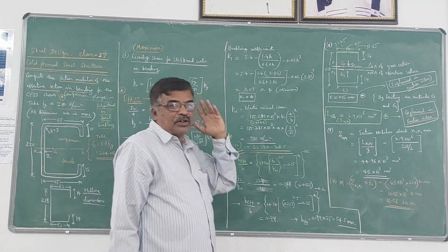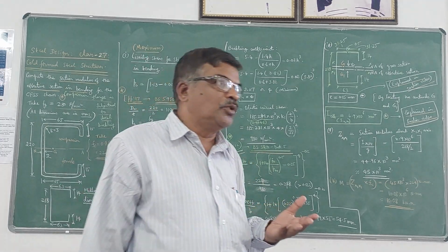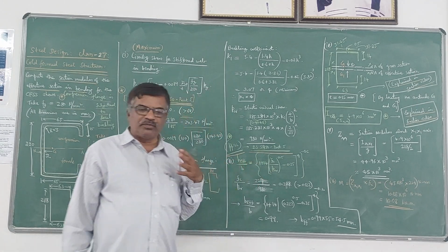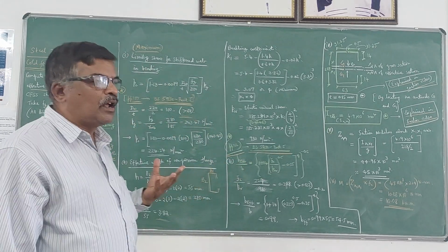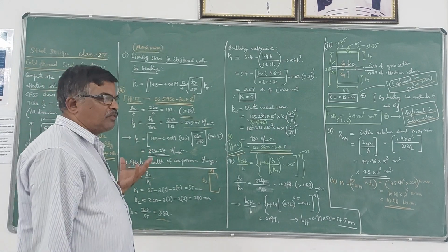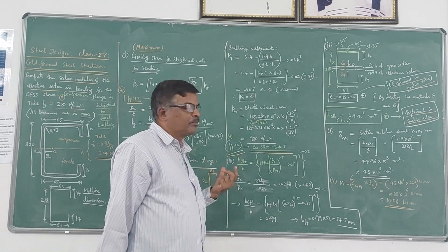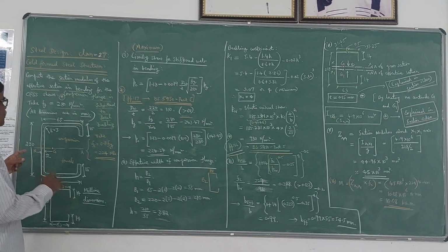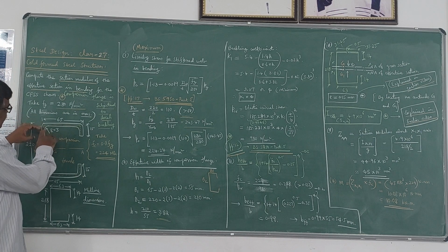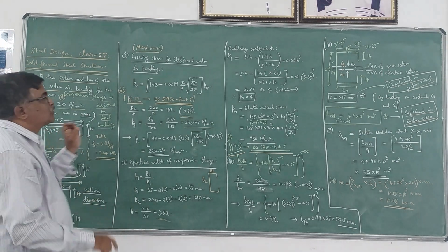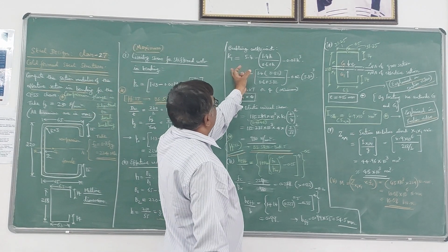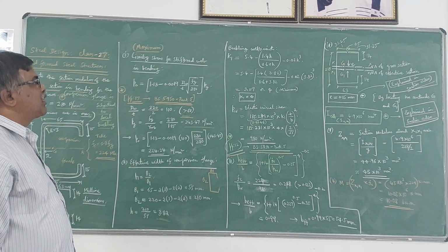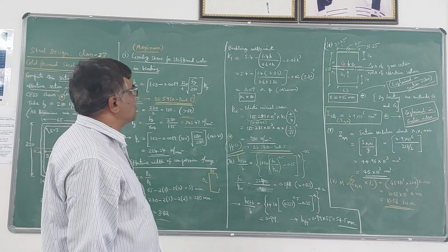Now you have to compute what is called the buckling coefficient. You know that for the buckling coefficient, the minimum value in the code for a stiffened element is taken as 4 and the minimum value for an unstiffened element is taken as 0.425. Now here, since this becomes a stiffened element, because both the sides are laterally supported, you can take this formula, K1 is equal to 5.4 minus 1.4 h by 0.6 plus h minus 0.02 h cube.